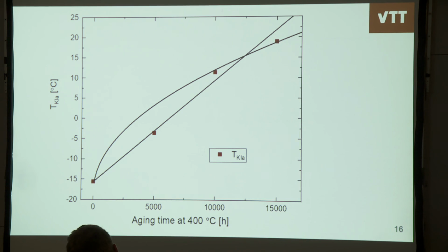So if you put the math together, the total impact toughness shift is 50 degrees, this is 30 degrees, and the initiation toughness shift based on fracture toughness was 10 degrees. So that sounds reasonable, but it might not have to do anything. That might also be a consequence, so it would be interesting to have other materials to see how that connection works.